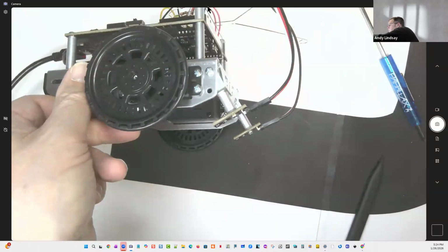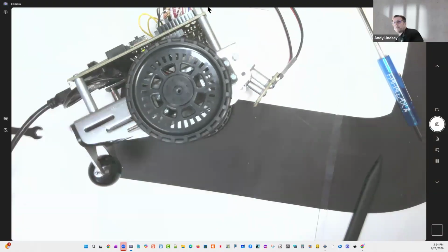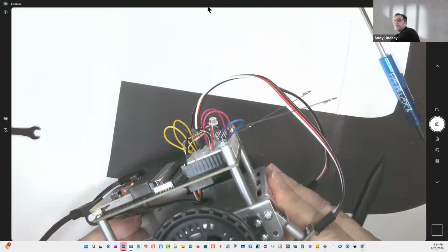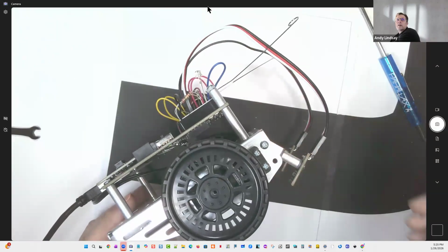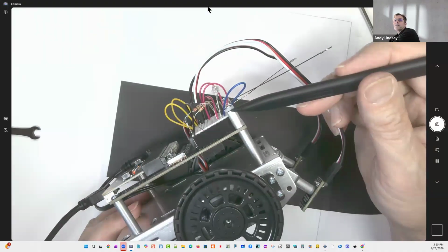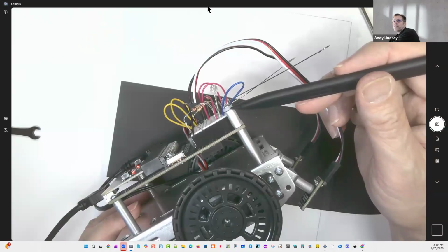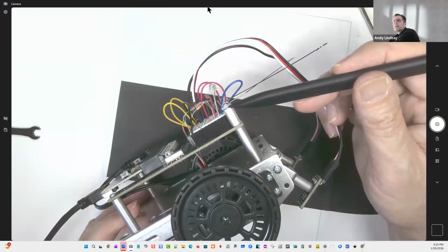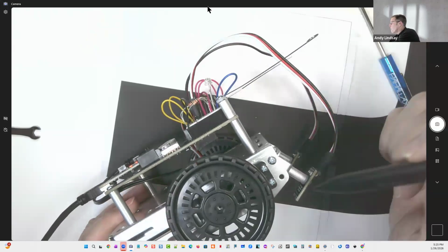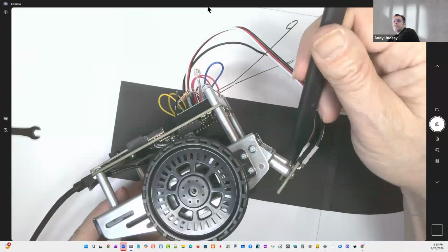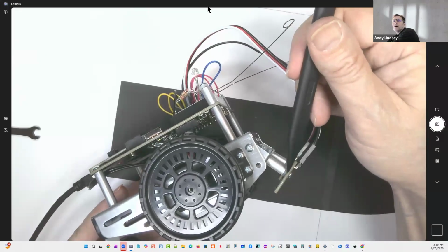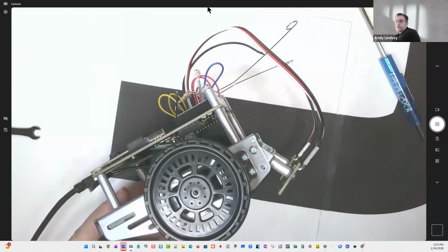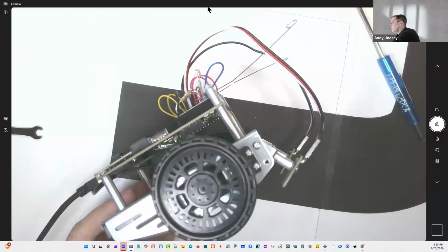Otherwise, roughly that angle should work. And then really what you can also do for homework to just make sure this is running well is to disassemble the whisker circuit, and that way you can grab an extra nylon washer and add it to the standoff, and that'll put your QTIs closer to the surface.